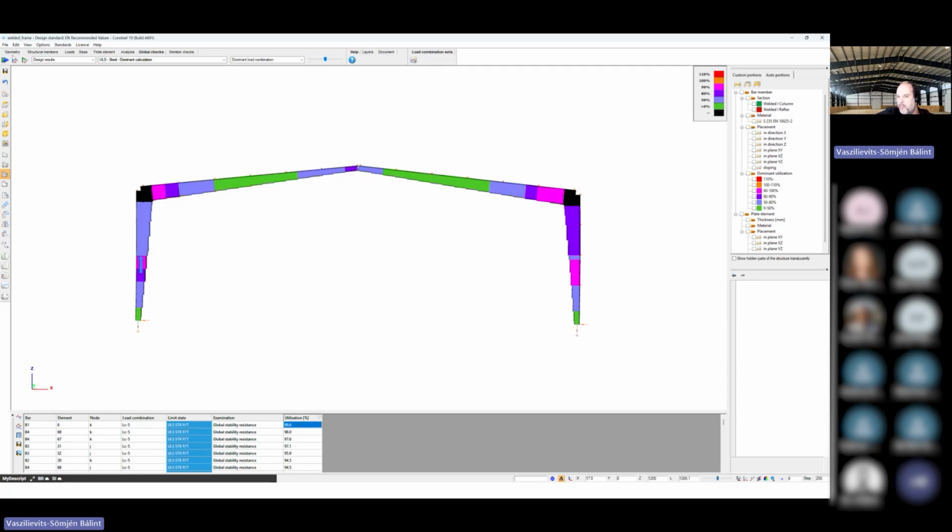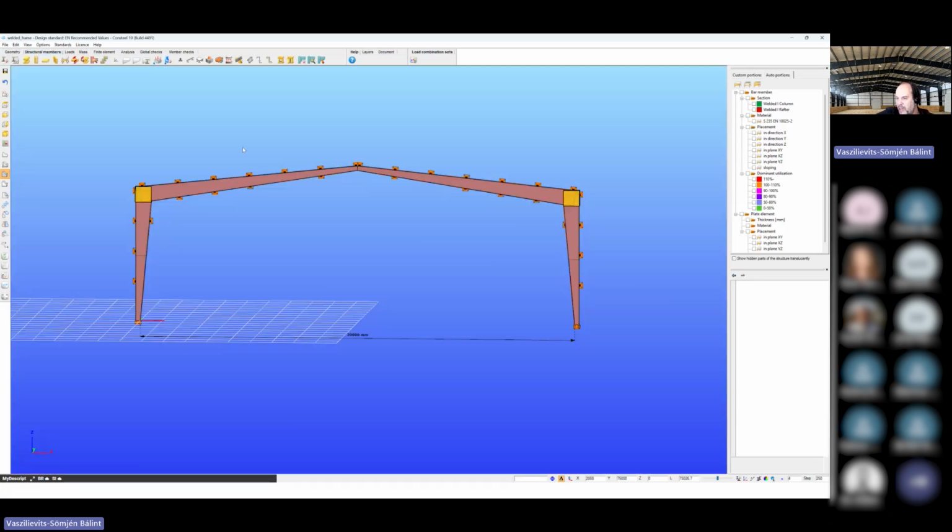With this new welded function, it becomes very easy to play, to adjust the different components, making the columns and beam elements, add, change, remove, change the thickness along the length. With the new offsetting option, you can very nicely fix those positions of the structure which you don't want to change during optimization, and make very clear in which direction your structure's elements will be deeper or narrower as a consequence of your changes.